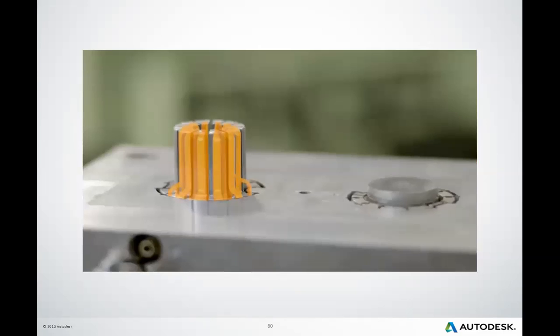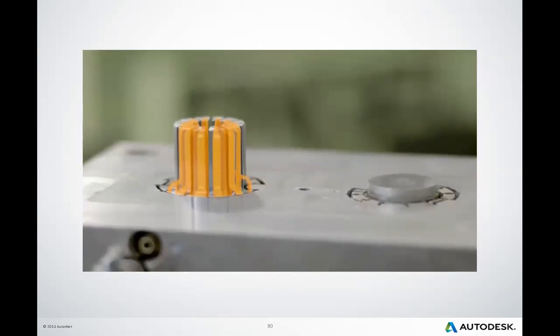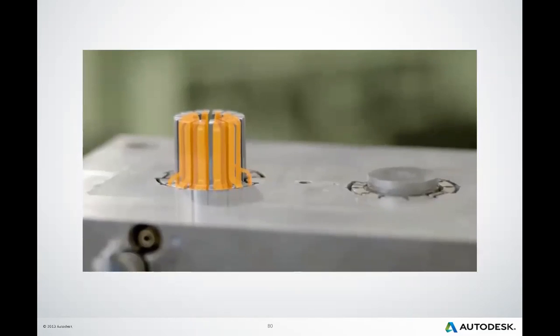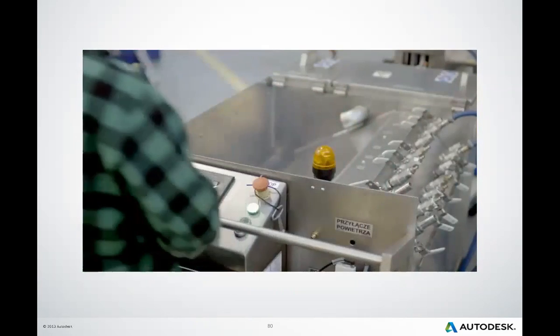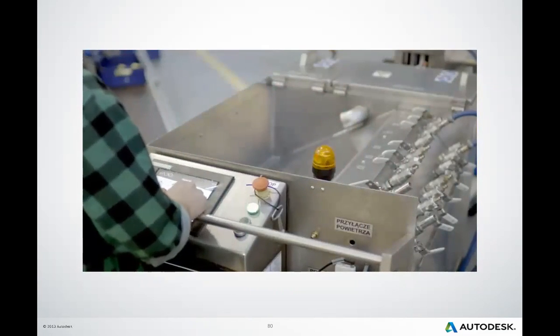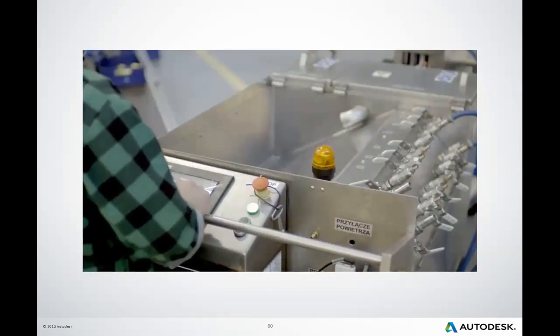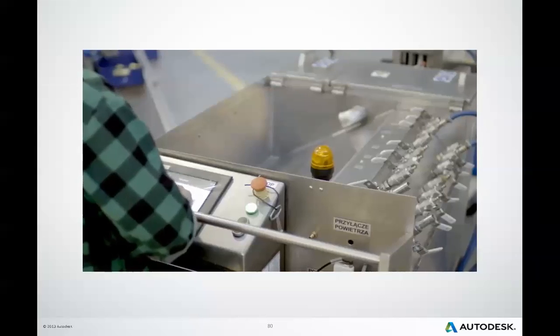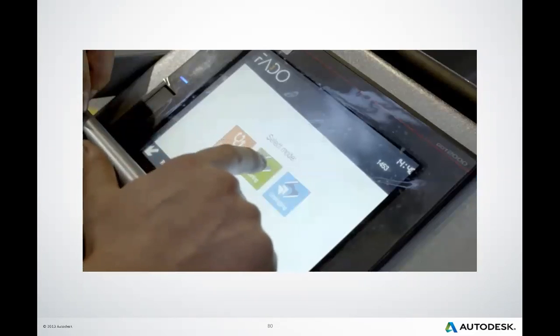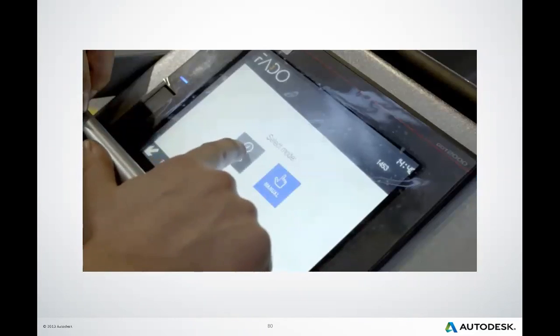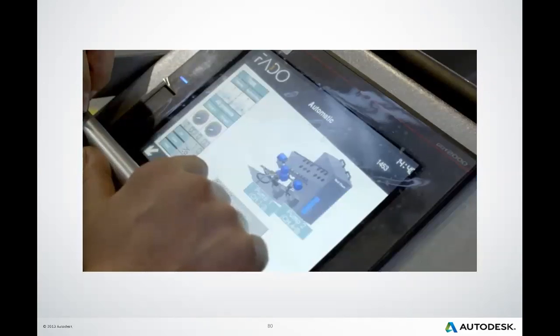It also takes some time to learn how to create channels optimized both in terms of cooling efficiency as well as insert maintenance and cleaning. We must remember that due to gradual scale agglomeration, thermal conductivity and cooling efficiency of channels will drop with time. That is why such inserts must be cleaned on a regular basis in order to prevent clogging or cooling efficiency loss.